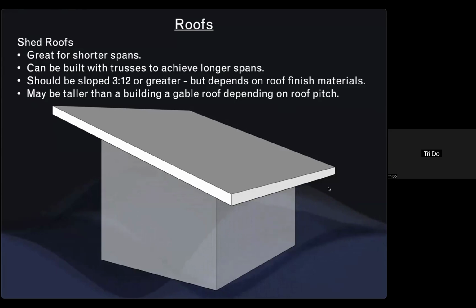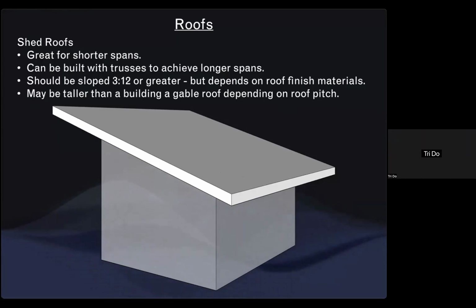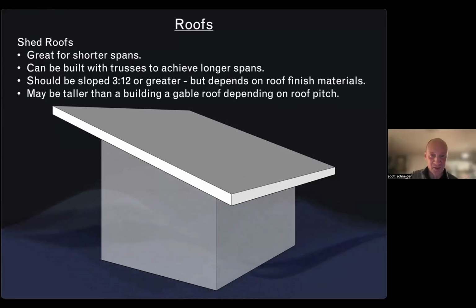Just another question. How long of a span can you reasonably do with a sloped roof? Well, it really depends on the design. If you're doing trusses, they can span longer. It really depends on the design of the truss, and even the size of the members.